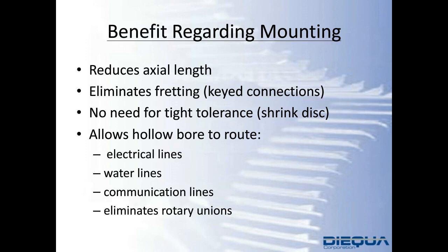Also, a keyed connection, as opposed to a robot flange, induces fretting. Fretting is seen as the consequence or result of two materials sliding or rubbing, coming into repeated, repetitious contact that over time creates heavy wear marks, scuffing on the surfaces.